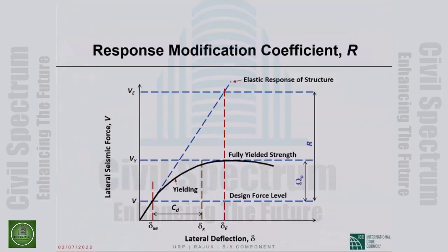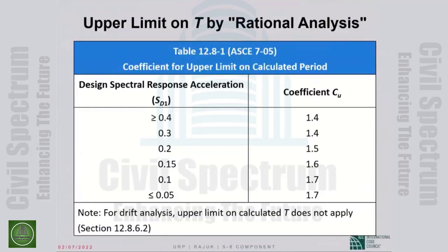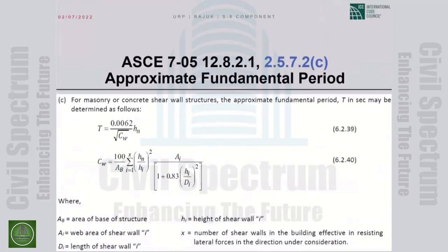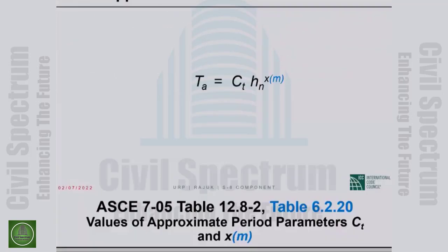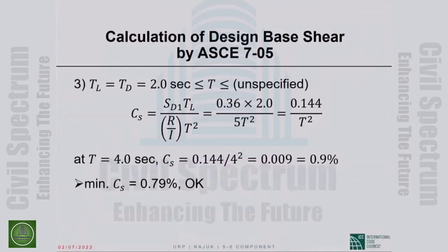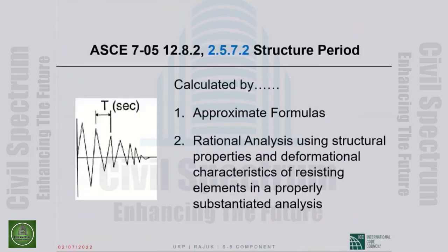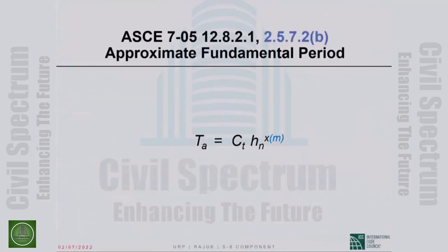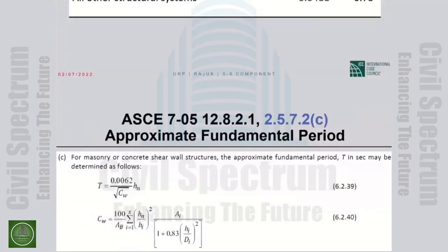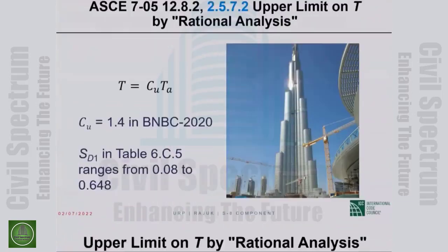Let me get to the place where we left off here. So this is the slide that I did not start on yesterday. Let me maybe do it this way. I may have to go a long way back. That may not be worth it. Okay, the base shear V is S sub A, the spectral acceleration, multiplied by the seismic weight W.